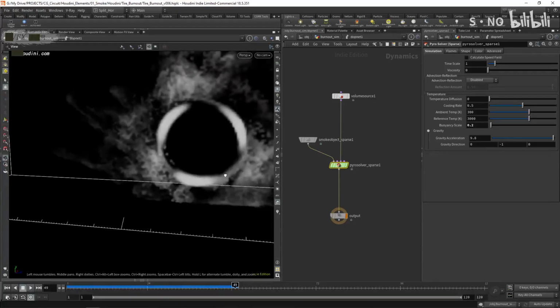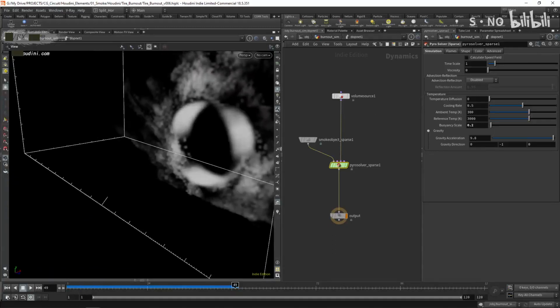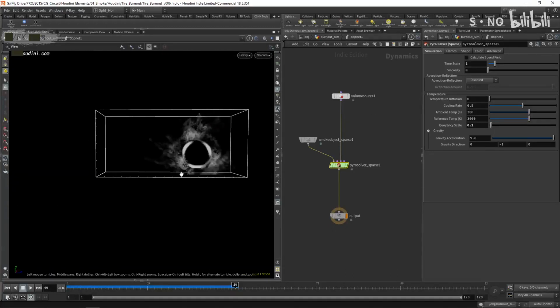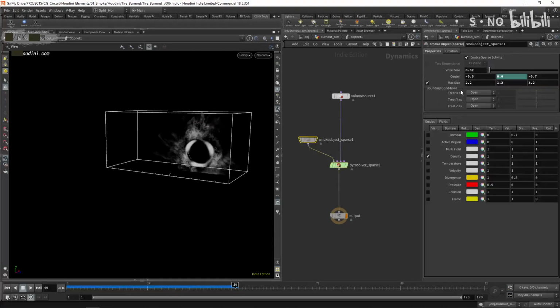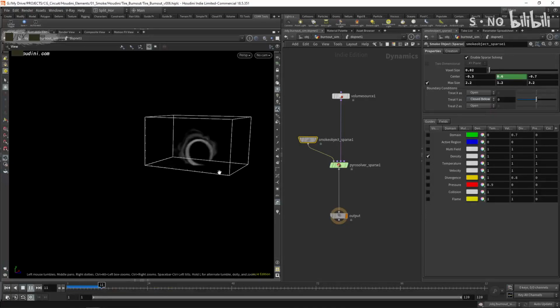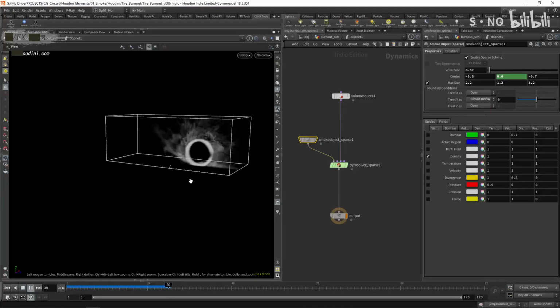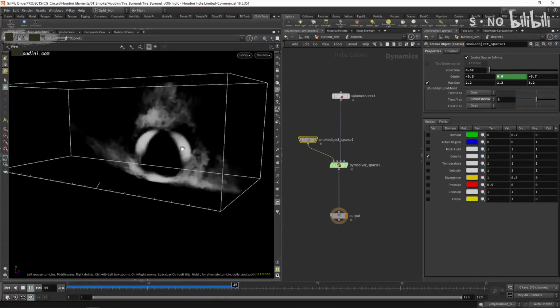The other thing we need to do is make sure that we tell it that this limit is actually closed. So as you can see here on the smoke object boundary conditions, this looks slightly different, but it's pretty much the same. So treat Y as closed below, and that way we'll have the smoke colliding with the lower end. We have our velocity working pretty well.